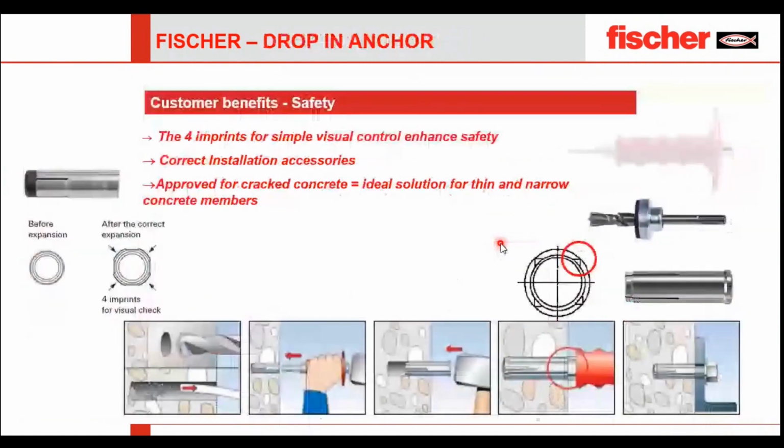Now moving to the most common hanger, which is drop-in hanger. For most of the MEP applications, we are using drop-in hanger. You can see drop-in hangers look like this, and once we are using a setting tool, which means the setting tool should be installed. You can see the installation method here. You drill, you fix the hanger, you use your setting tool to make sure that your hanger works.